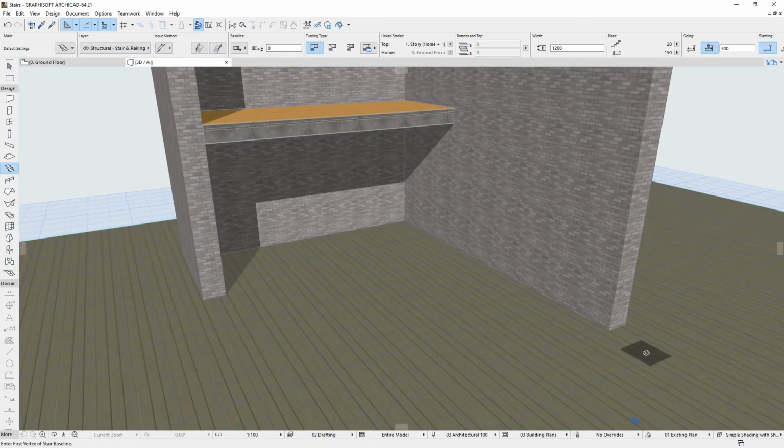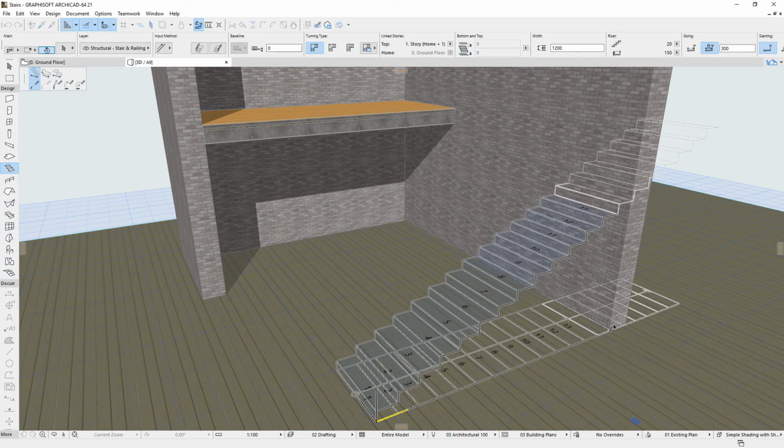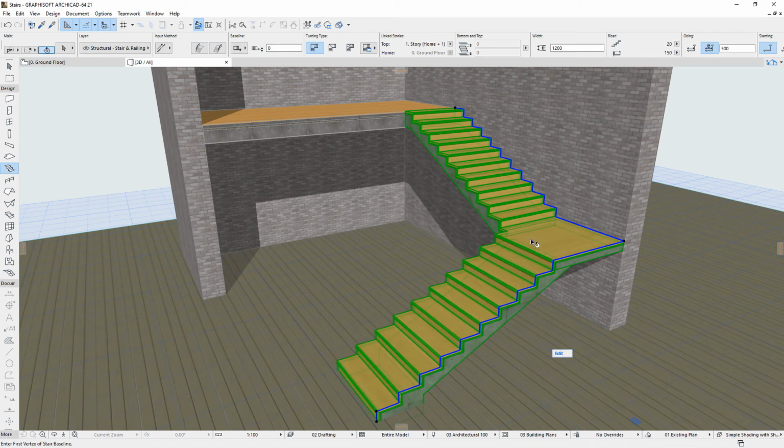The 3D geometry of the ARCHICAD stairs is constructed using a so-called polygonal input, defined by the architect on the 2D floor plan view or in the 3D view. Based on this user input, a 3D stepped stair baseline is then constructed. This is visible in 3D view. A 3D stepped reference surface is extruded horizontally from the stair baseline.